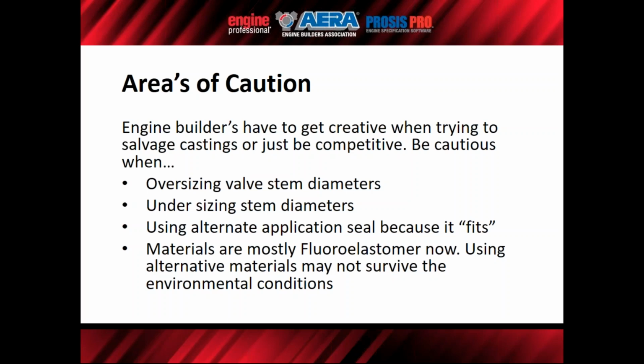You can contract some seal manufacturers to perform this test, and you could use all the OE parts as a baseline, and then switch it up and have your oversized stems and oversized seals, or the standard size seal or whatever, and you can get some results that can prove or disprove whether your project may work.